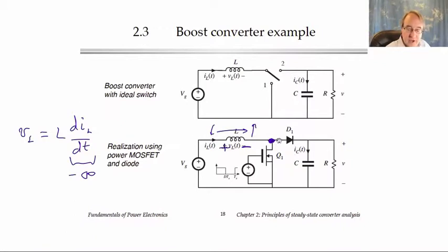Once it does turn on, it provides a path for the inductor current to flow. The inductor is happy and the current no longer tries to change. So we can put a MOSFET and a diode that will operate automatically with the MOSFET. Sometimes in the business, a diode that operates in this fashion is called a freewheeling diode.